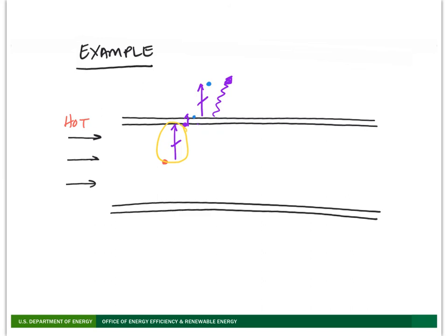And so the steps for that are first characterizing the flow based on the Reynolds number, then calculating the Nusselt number from a correlation, and using the definition of the Nusselt number to get the heat transfer coefficient. Once we have the heat transfer coefficient, we can then use Newton's law of cooling for the final calculation.